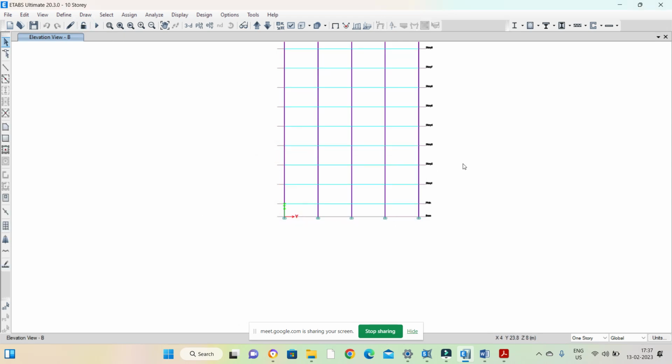If you unlock, whatever output was there will be erased from view, but it will be stored until you run your next analysis. Now as you can see, I have unlocked, you cannot see any readings or any output here, but it is stored in the memory. It is still not erased, but if you run your next analysis, that memory will be erased. So this is important.